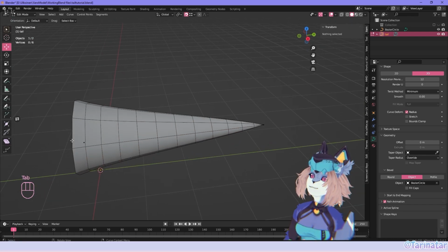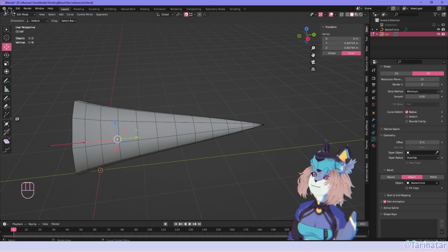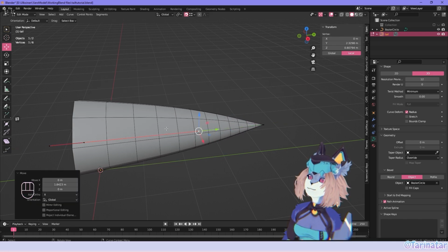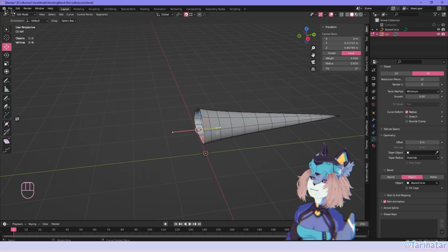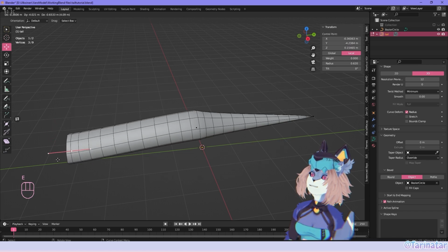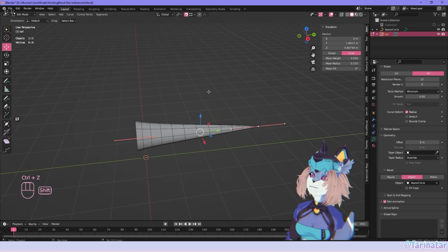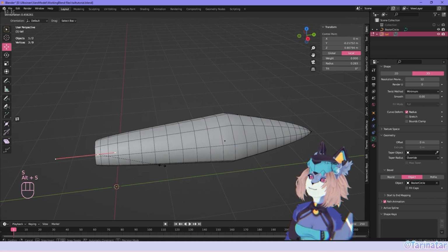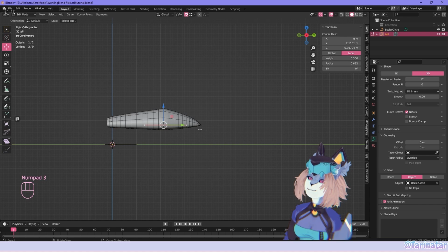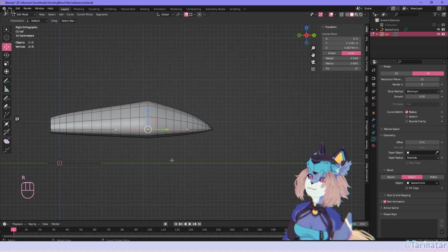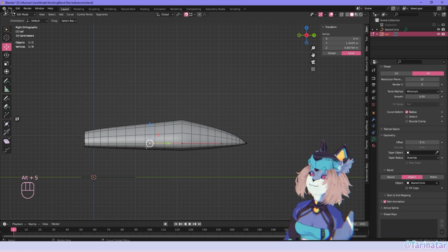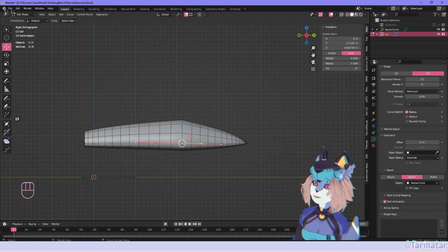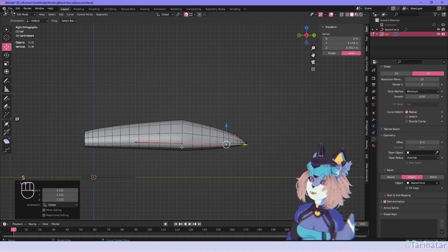Because here we can actually see when we scale, for an example, this one, or move it or scale it, we can see the geometry move with it. You can add by extruding, but you can't do that in the middle, obviously. We need to subdivide it with right click, subdivide. And we can give it a curve, but usually if you're gonna weight paint or animate things, you don't make it into a pose. So you have it in as rigid of a pose as possible, if that makes sense. So we want to keep it straight.